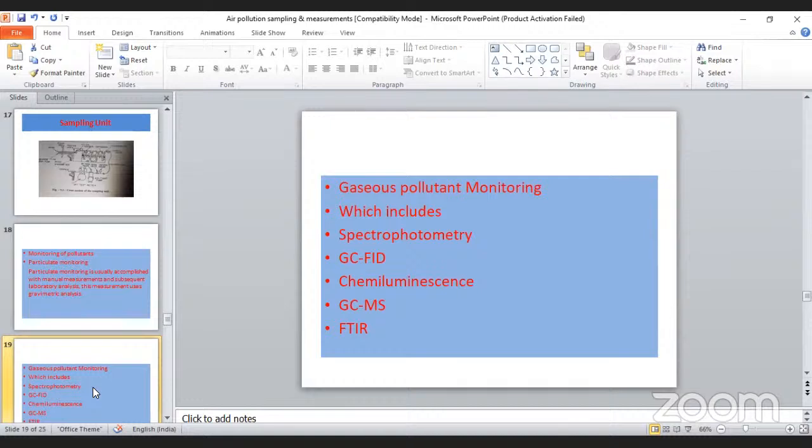Then only whatever the method you have adopted is correct. Otherwise, you have to change the method of analysis till you get the exact amount of known quantity, known concentration of sample. Make use of that relationship. That means known input. When we are giving input, if 10 microgram is there, you have to get the output with the same 10 microgram per liter. If you get that, then your calibration is correct, then you can follow the method for unknown quantification.